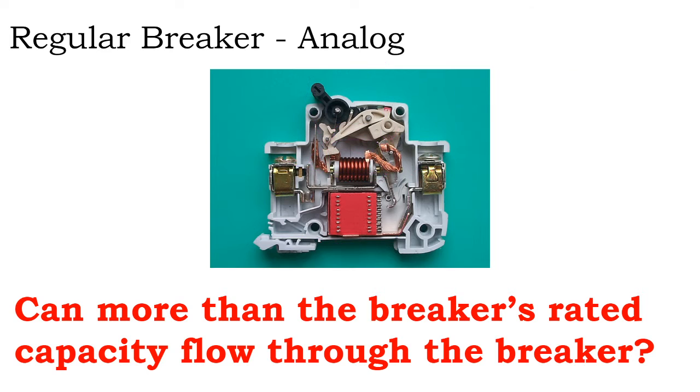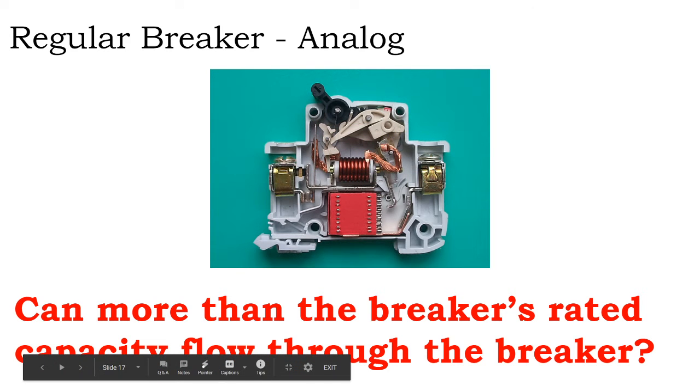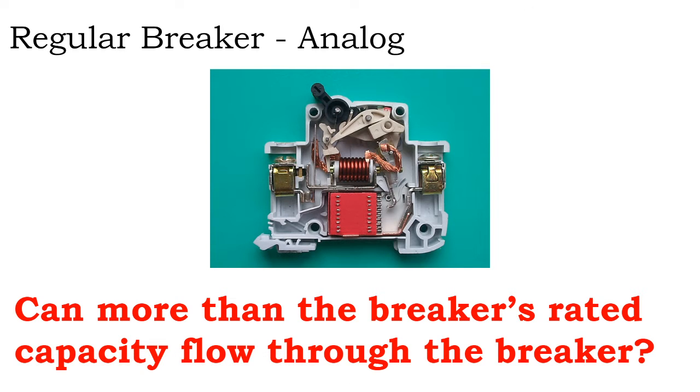But it'll only open up at the maximum of its current capacity. And so, can more current flow through the breaker's rated ampacity? Can more current than what it's rated for flow through the breaker? Yes, but only for a limited period of time before it opens up.